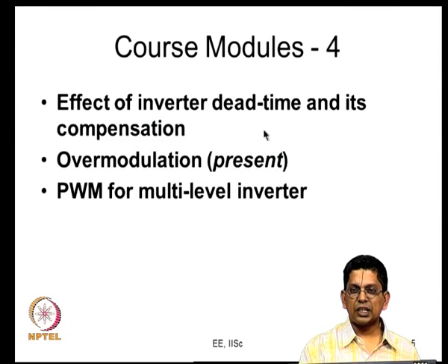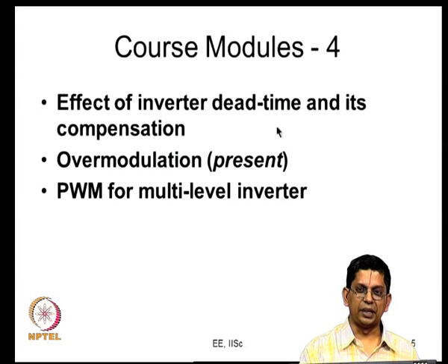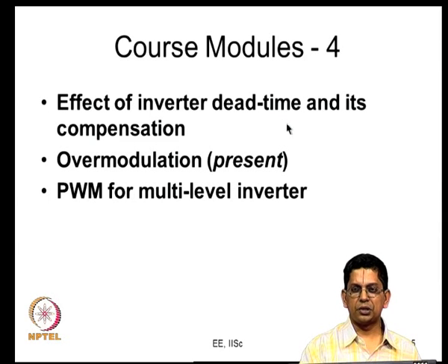Here we are considering the effect of dead time, that is, the top and the bottom devices are not exactly complementary in an actual inverter, not switched complementarily. You switch off the outgoing device first and then you switch on the incoming device, which is the dead time, and we looked at what the effects of the dead time are. We analyzed its effect for continuous PWM methods. We found that for all continuous PWM methods the effect of dead time is quite similar and it is dependent on power factor. We also looked at the effect of dead time for bus clamping PWM methods.